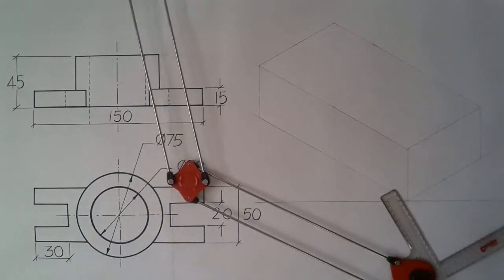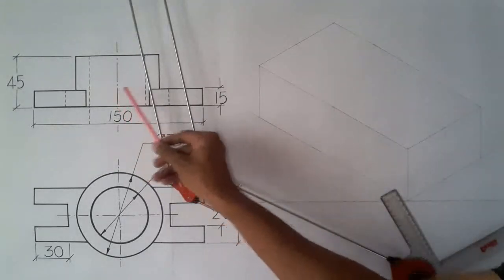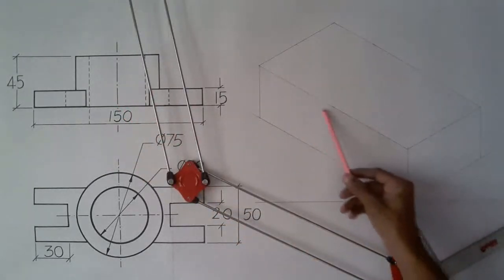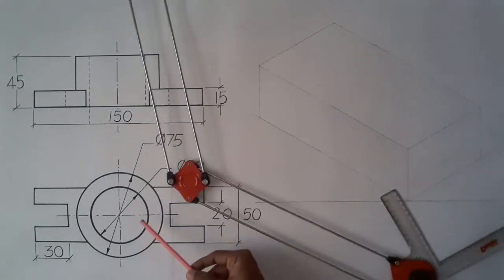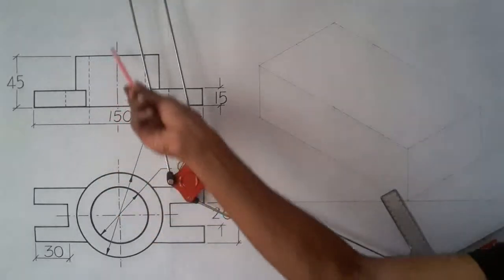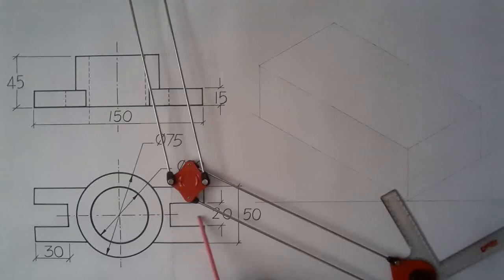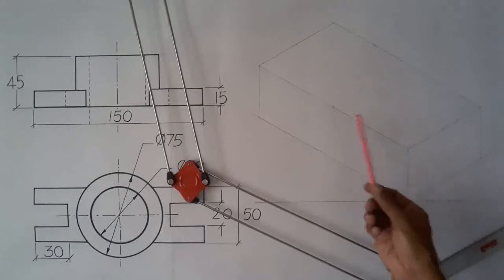After constructing the box, now it is time to copy the details of top view on the top of the box and the front view details on the front face of the box. So one more thing, we have to go in advanced method. We have to follow some techniques. For example, this is an object having a symmetry in y-axis. Similarly, in the top view, you could see some symmetry in x direction as well as in y direction. So in these situations, it is better to mark the symmetry lines in the box itself.